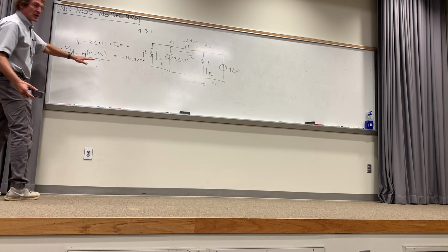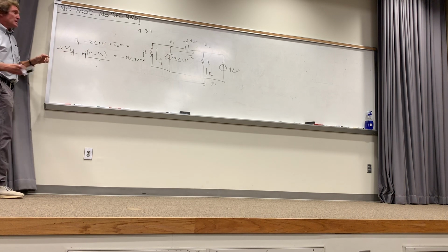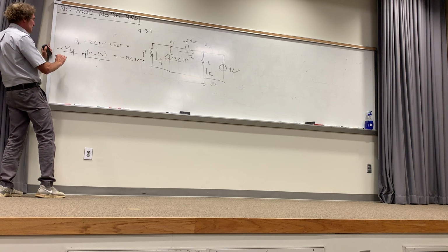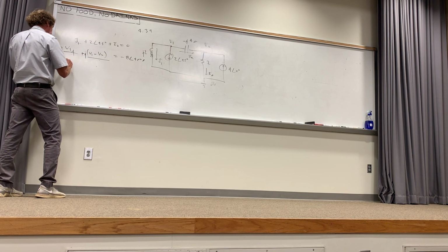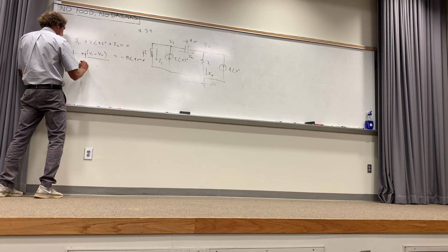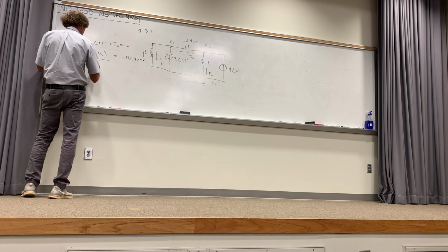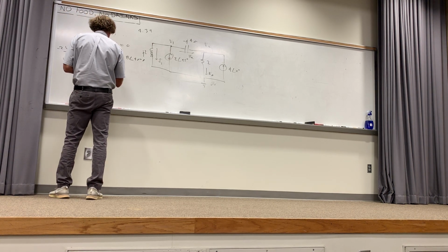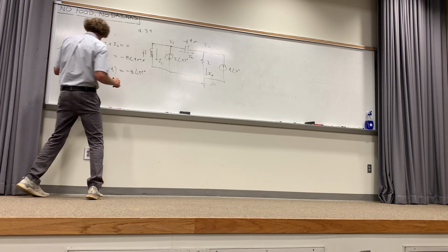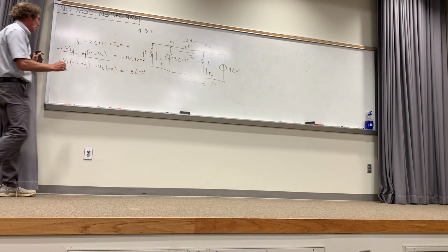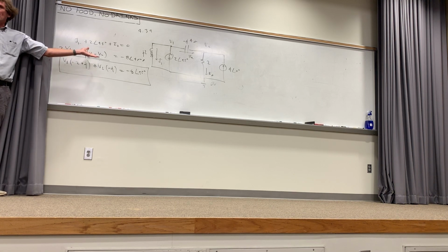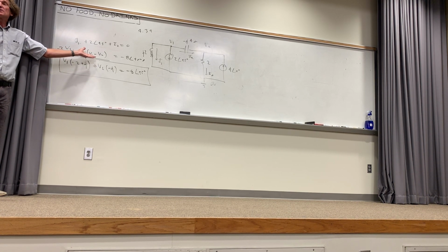Now, we've got this, right? Everybody? Now write the equation in terms of the coefficients of V1. And by the way, there are so many different ways to do this. Right here, I'm going to put V1 here. The coefficients are minus 2, and then plus j, right? And then plus V2, and the coefficient for V2 here is minus j, equal to minus 8 at an angle of 45 degrees. That's the first equation. Then put a box around that final form of your equation. Now if I multiply this by any scalar number, by 10, 100, or a quarter, it's still true.